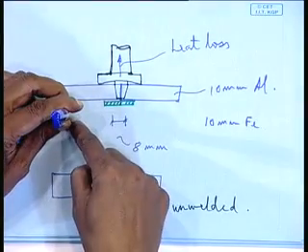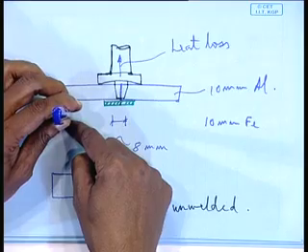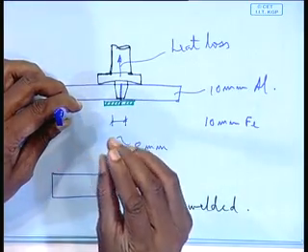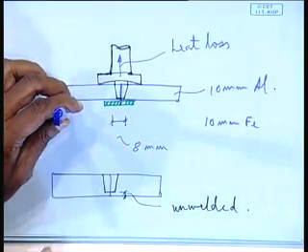Initially the friction will be very high, but the material has become softer under the heat, so friction has decreased. So there can be a reduction in heat generation. If you keep the indentation time for a very long time and then try to move, it will not move, because the plate has cooled down, right.